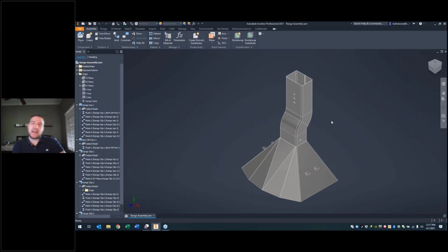If this assembly had rivets or weldments or weld nuts or anything else inside of this space, if they were non-nestable components, the system is typically smart enough to figure out this isn't something that should be nested. If the thicknesses don't jive with the material library, or the shape of that part doesn't make sense, say it's a revolve, for example, it'll just exclude them automatically. In my case, I didn't add any of that material in here just to keep this data set simple.